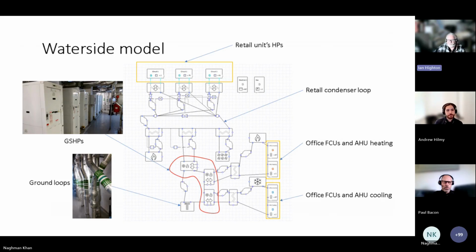Yeah, they were basically looking at massive cooling loads all the way through the year, which was sort of like, hang on a minute, why is it cooling in the wintertime? That doesn't make any sense. And it turned out to be a humidity control. So the guys at NG Bailey, who were also working on the project, spotted the fact that the RH set point was actually 30%. So the cooling coils were literally working flat out pretty much 24/7, trying to dehumidify, and then they had to reheat the air. So they changed the humidity set point because 30% is very dry, itchy eyes and all that stuff, very uncomfortable. So it made the occupants even happier, which is great.